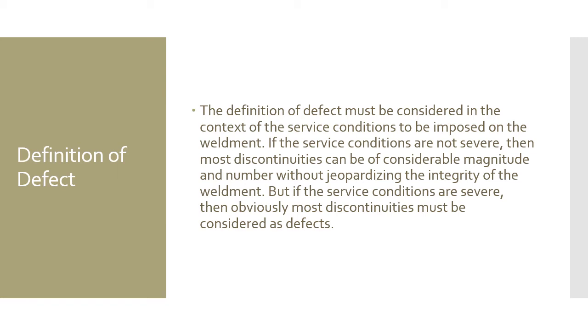Definition of defect. The definition of defect must be considered in the context of the service conditions to be imposed on the weldment. If the service conditions are not severe, then most discontinuities can be of considerable magnitude and number without jeopardizing the integrity of the weldment. But if the service conditions are severe, then obviously most discontinuities must be considered as defects.